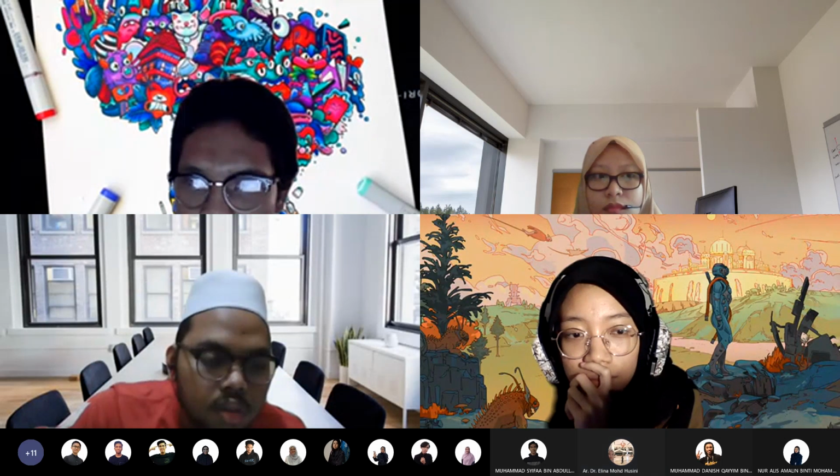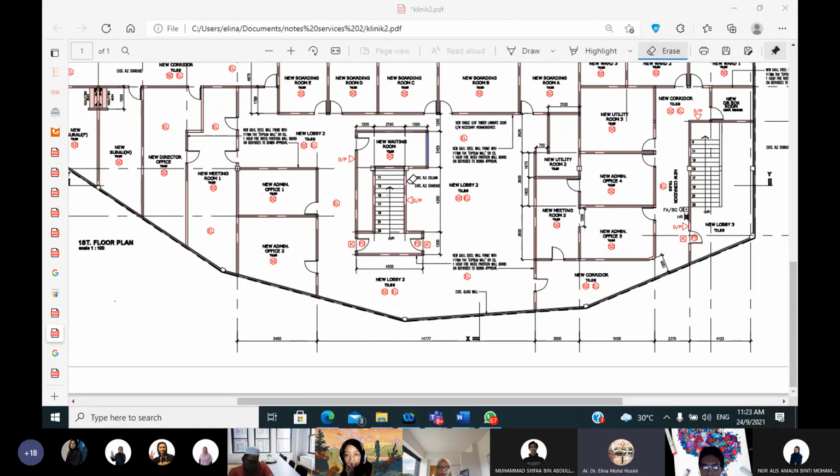Okay, sekejap. So, tadi dia kata from sometimes when you design a building, there would be a long corridor somewhere here. And you may say that from one door here to another door that's situated here. So, okay, I draw here. So from this waiting room, from this fire door to here, and normally from here to the end of the room, it has to be 6 meters, cannot exceed. What happens if you exceed 6 meters here? So you have to provide another partition, so to have the perimeter not more than 6 meters.